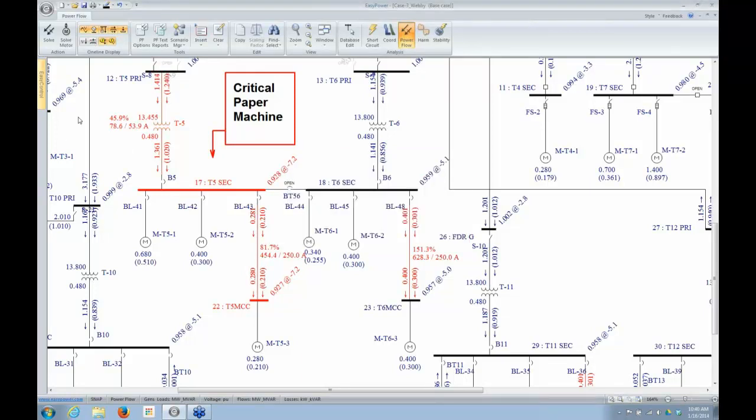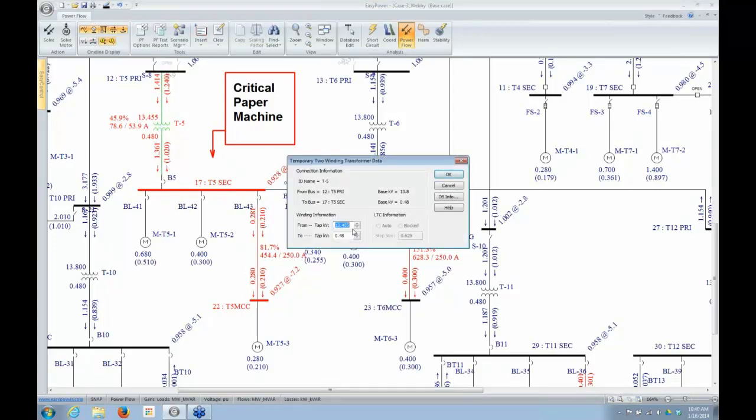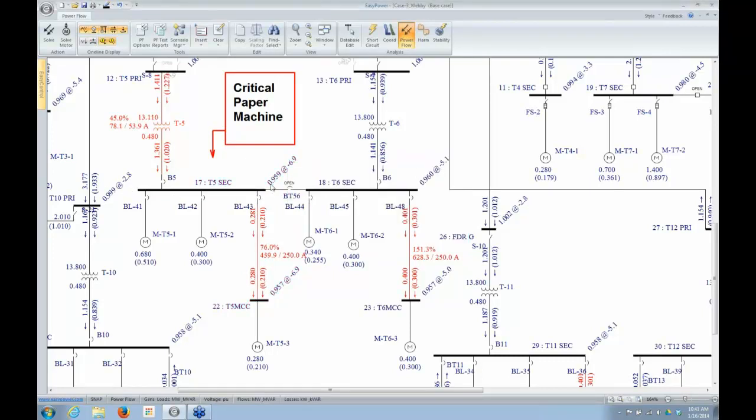It's going to rerun the power flow, and then my voltage is going to increase by 2.5% basically. If I do it again, if I go to an even lower voltage, the full 5%, let me get out my calculator here, 0.95 times 13.8 is 13.11, then the voltage comes up, and I finally get it above 0.959. All right.